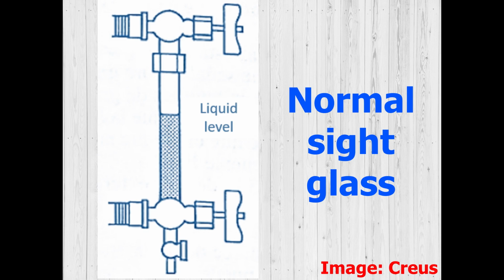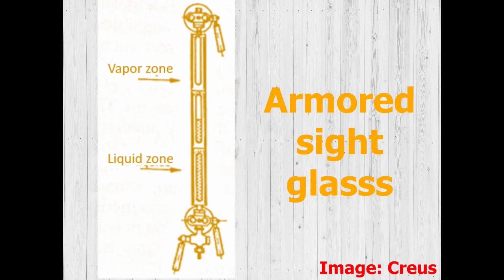The side glass indicators consist of a glass tube with its ends connected to metal blocks and closed by cable glands that are connected to the tank by 3 valves, 2 of which are safety closures at the end that have a ball inside to retain the liquid escape in case of a glass breakage, and 1 of purge. The common side glass indicator is used for pressures up to 7 bar. For higher pressures, the glass is thick, rectangular in section, and protected with a metallic armor.